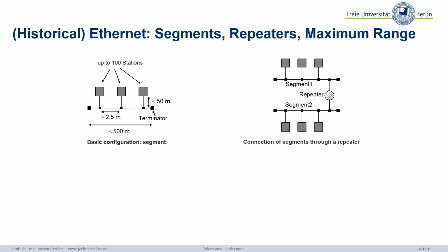And then the engineers tried to work out how we can adapt several stations. What is the maximum length of a cable? There we have problems of attenuation of the signal. Repeaters have been introduced. So the idea of a repeater is we take in the signal, which is relatively weak, but the repeater knows what it means, creates ones and zeros out of this, and can then create a nice, perfect, strong signal again, the output.